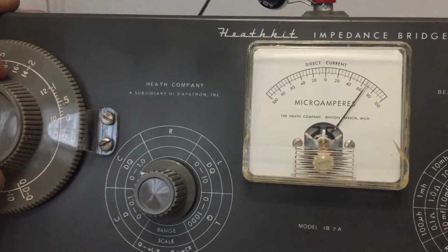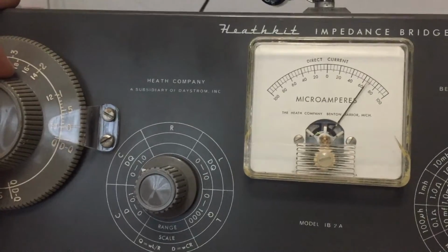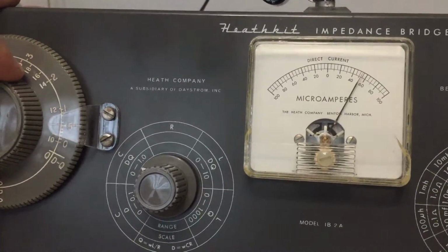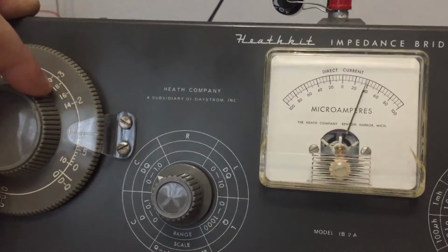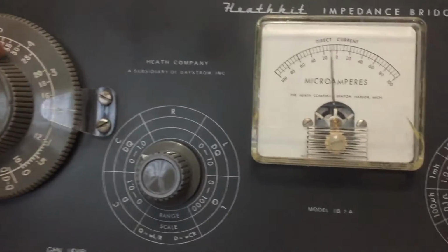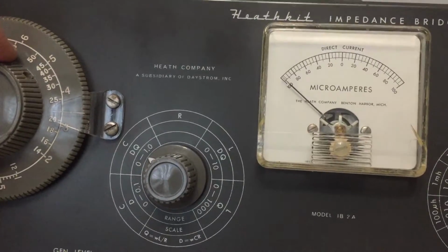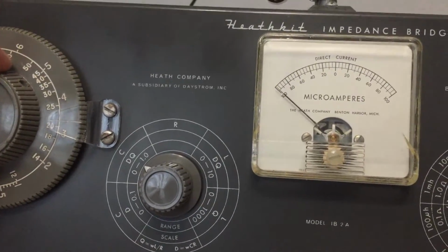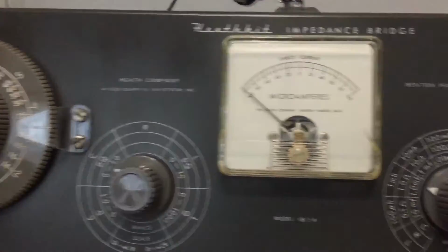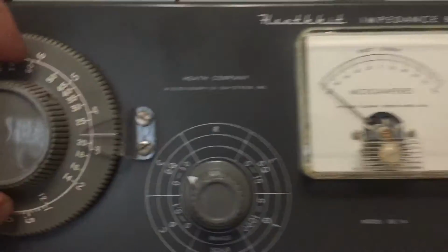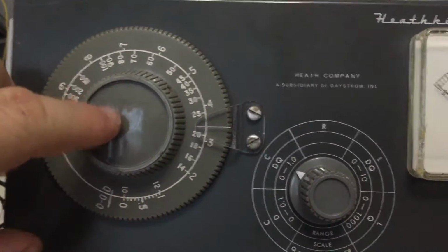So what I found was if I set it just like that, just to the point where it starts to react with the circuit, I get the most accurate measurement. And obviously, if I set this up again for 3.2, it'll tune that, I went past it. Right there, it'll tune that circuit for that capacitor, is what we're going for. So that's how I set up this knob for Q.